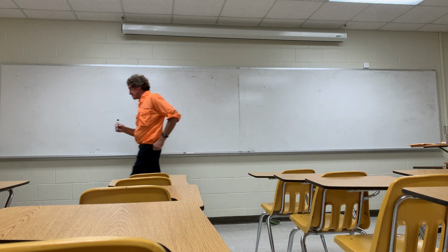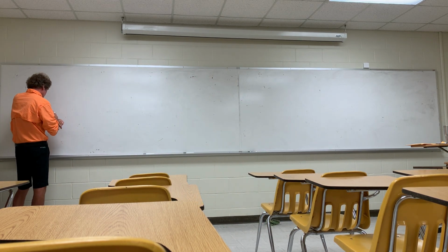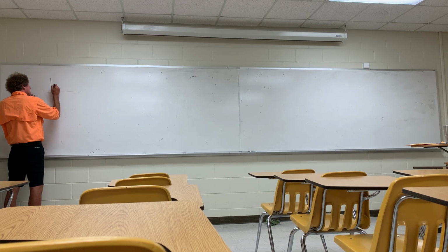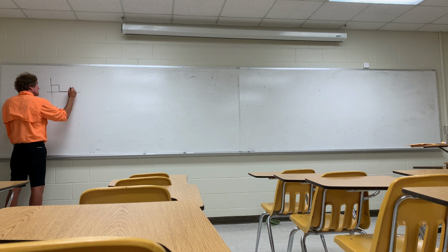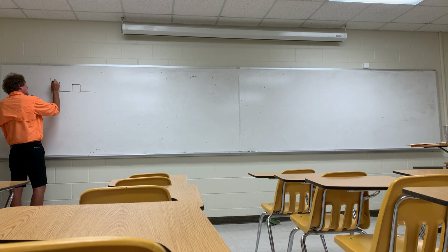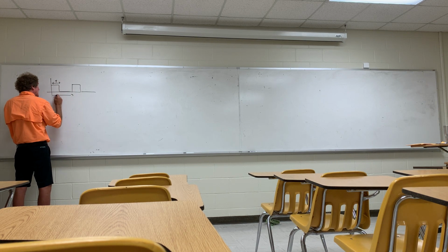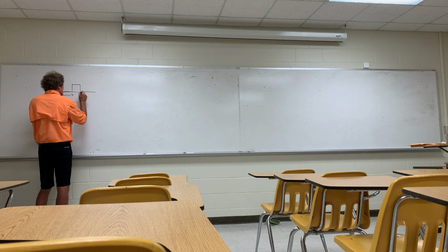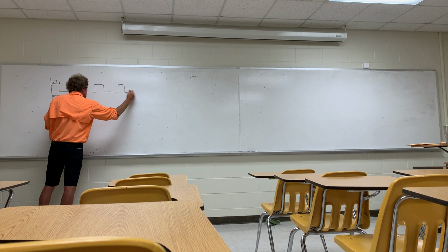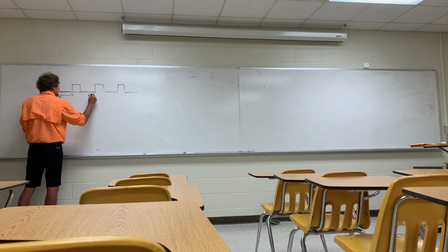So, without getting too far into the weeds, y'all realize if you have any kind of periodic signal, I'm going to just use this one. This is a standard pulse signal. It's going to have a width tau, and it's going to be repetitive over a period T, or the PRI. This is a standard radar signature, you might say, for the baseband. Goes on forever. This is the time domain.